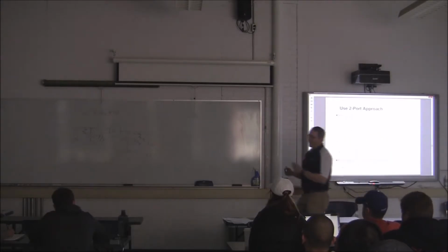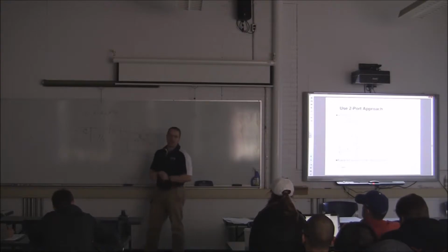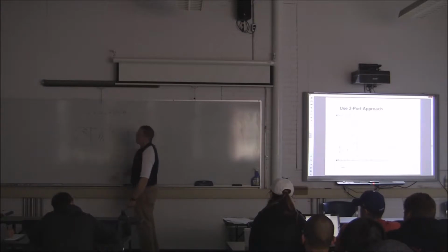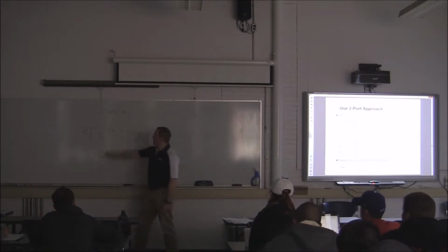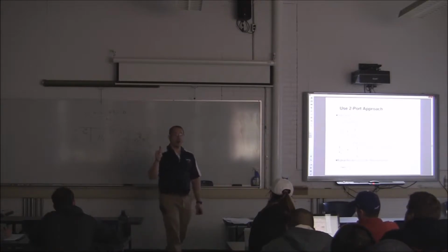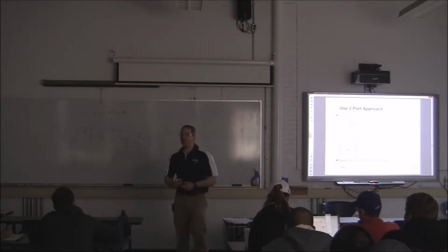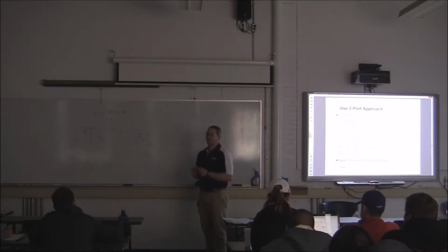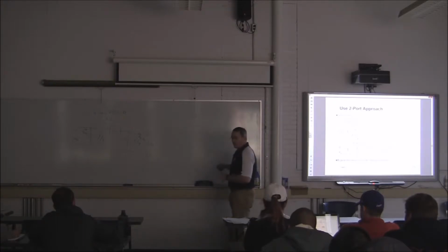I want to solve for A, let's say. I got to get rid of this part. How do I do that? What if I make IR equal to 0? What happens to B times IR? Becomes plus 0. So VS will equal A VR when IR equals 0, right? So when does IR equal 0? Under open circuit conditions, which is, if you remember what we drew, right?